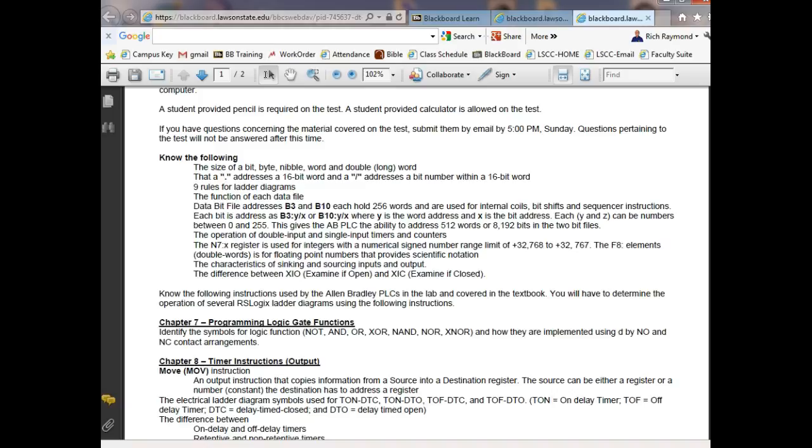We've got two contact symbols in PLCs. We have a normally open and we have a normally closed, and that's it. But when you get to the wiring diagram on how you wire up the PLC, they use the electrical symbol for these devices. You'll understand that. And they do this in your book quite often. If you don't understand the electrical symbol for the devices, then you wouldn't be able to look at the actual input wiring and tell what's actually hooked up there.